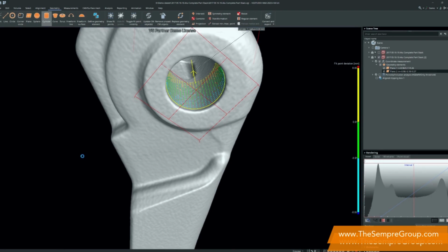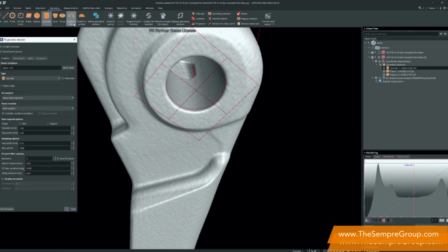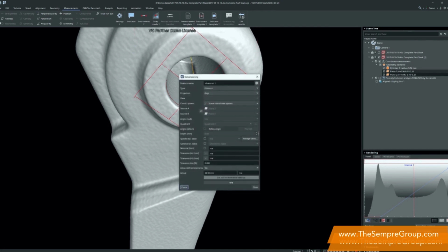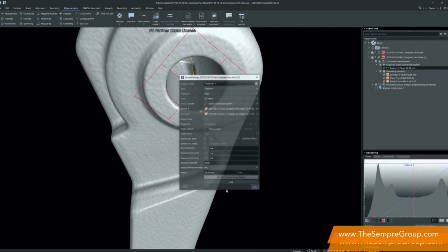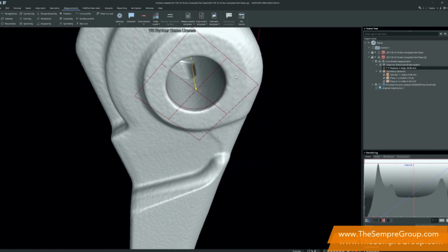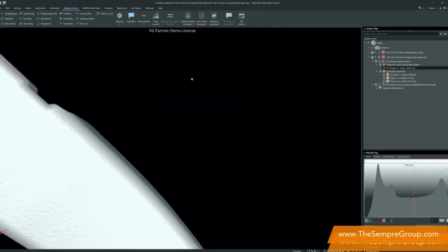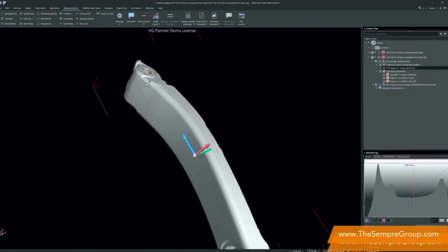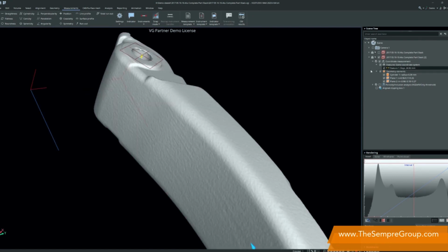There we go. So we have a couple of different geometries, and now we can decide to measure certain distances between these. If we say plane 1 and 2, we want to know the dimension between them, so we can create it. In this case, it's 24.92 millimeters between the two planes. So you can create a full template on top of this 3D model that you can afterwards use as a template on other 3D models that will be scanned afterwards.